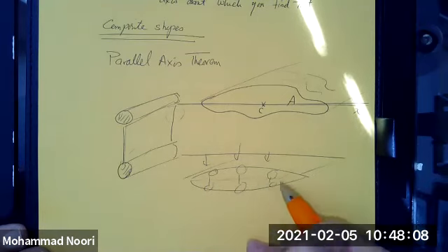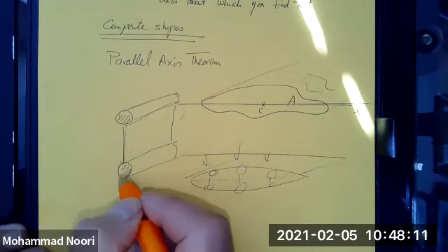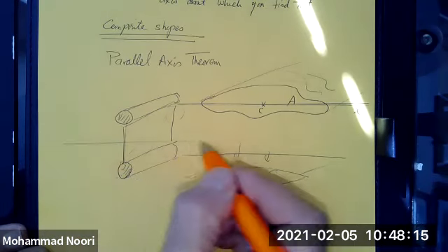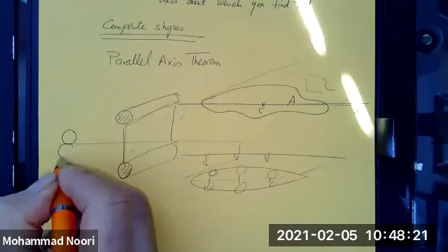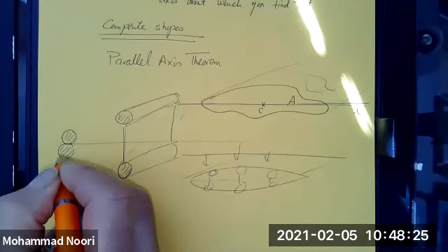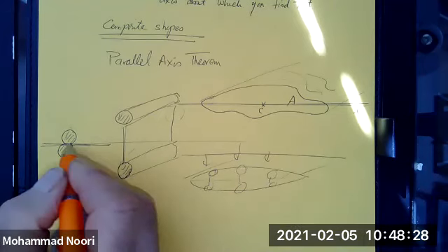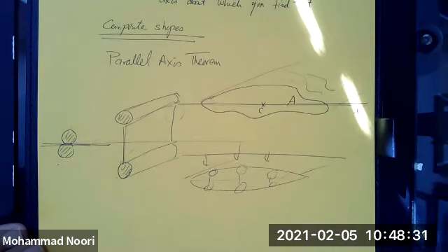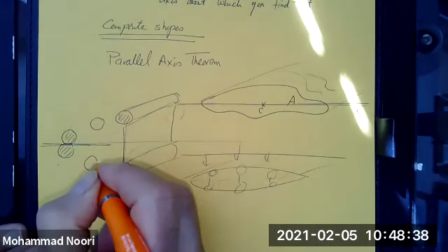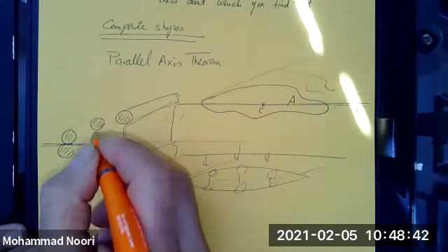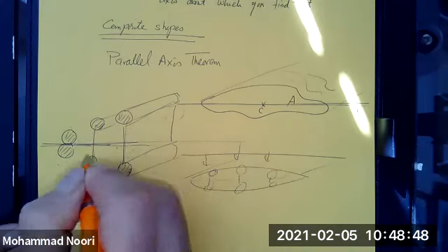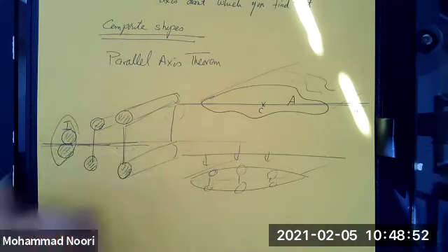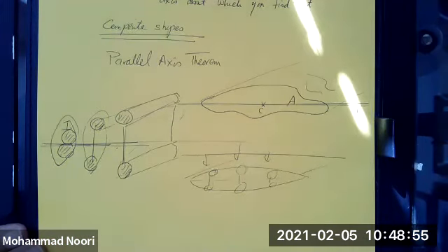So you have to put these in these areas because you want the bending about this axis. You can find the moment of inertia of, let's say, this shape about its centroidal axis, but if you put these further apart, obviously the area is further from this axis of bending, so it generates more moment of inertia. But if I have the moment of inertia about this for this shape, how do I find the moment of inertia about that axis for that shape?